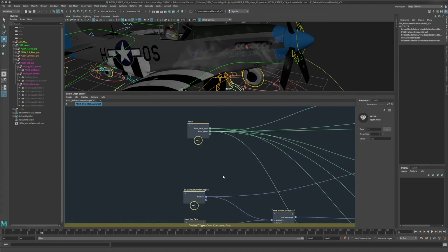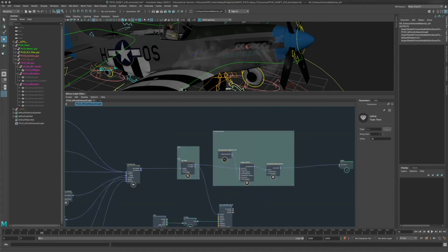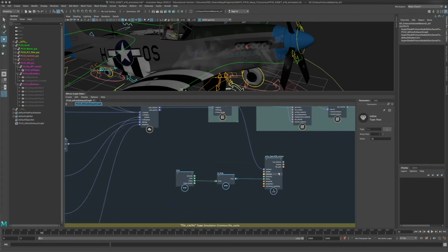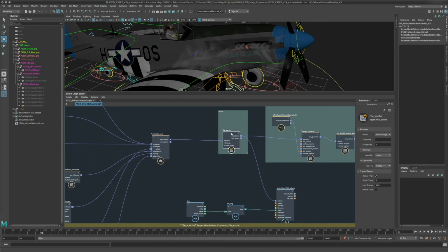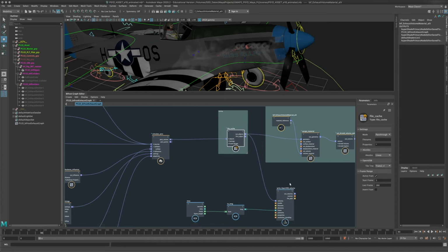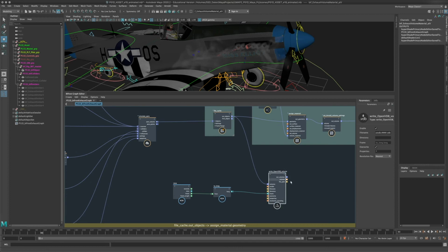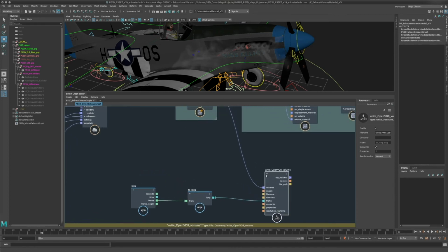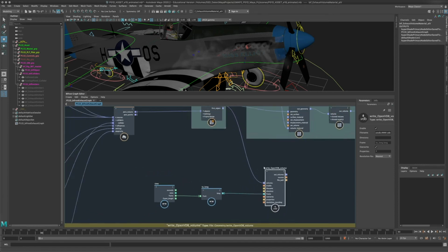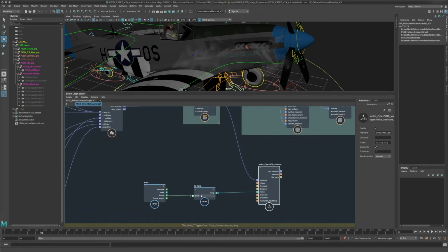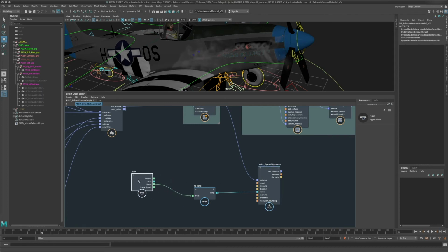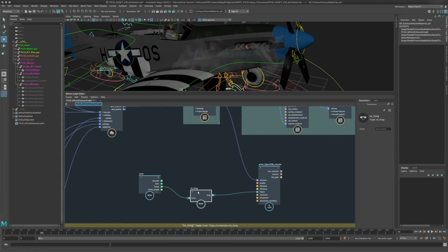So going into this, there's actually another thing. For GPU purposes, I also have hooked up to that file cache. So I'm going to cache out a BIF sequence, and then if I'm happy with that, I'm gonna write out an OpenVDB volume sequence. Interestingly, you have to provide the right OpenVDB volume with the actual time of the Bifrost simulation, which doesn't make that much sense.